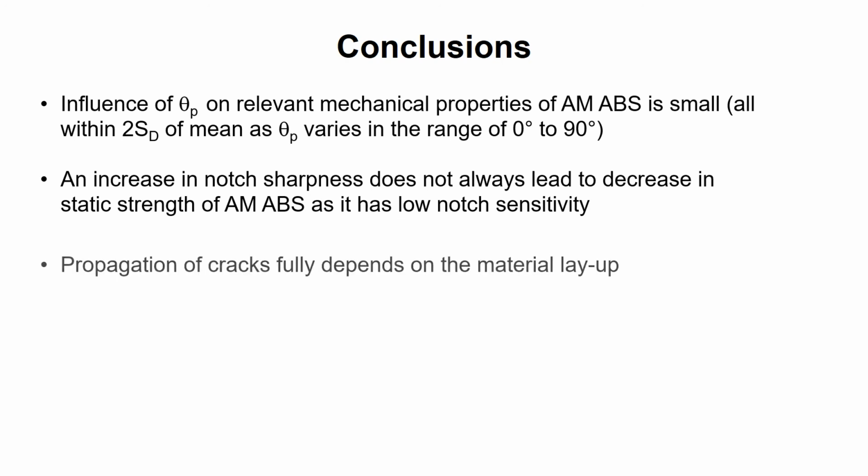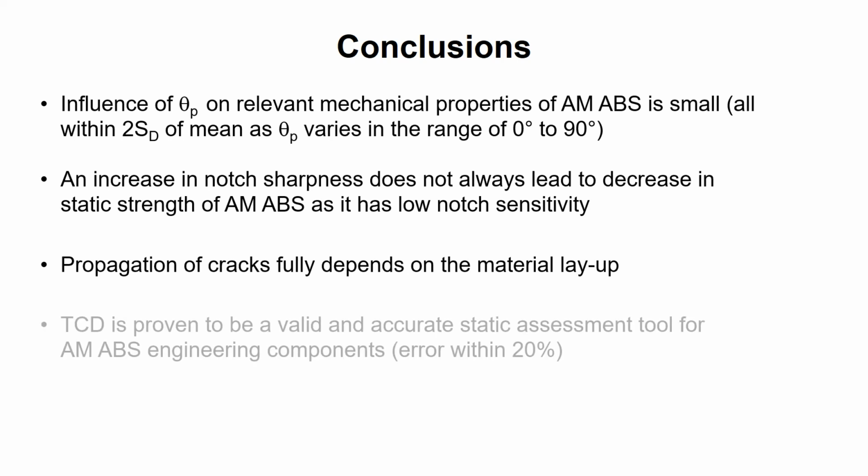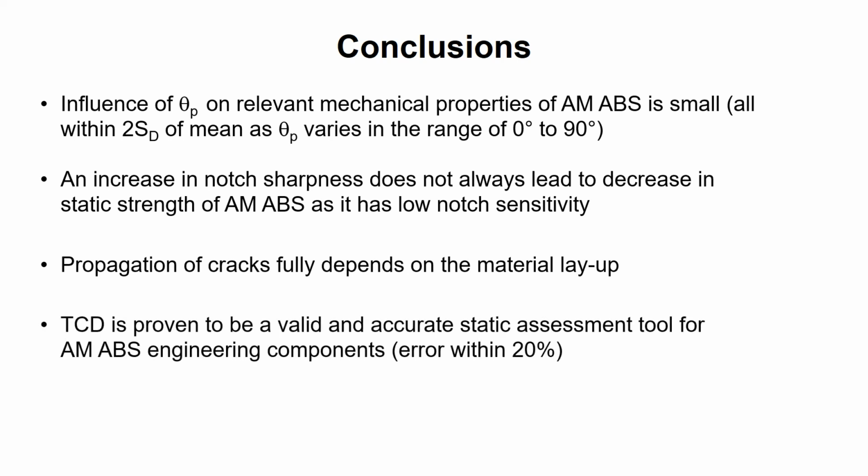It is also worth noting that the propagation of cracks fully depends on the material layout. Finally, the Theory of Critical Distances is proven to be a valid and accurate static assessment tool for the AM-ABS engineering components.